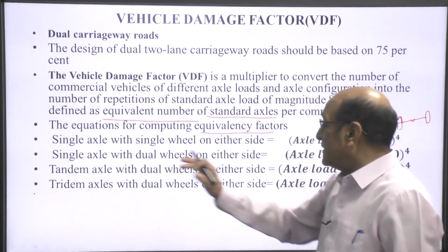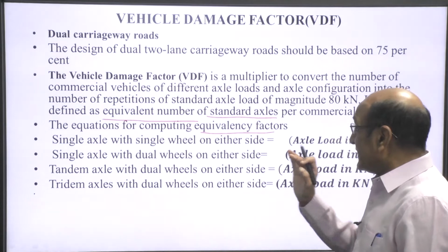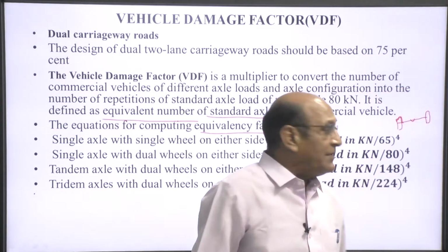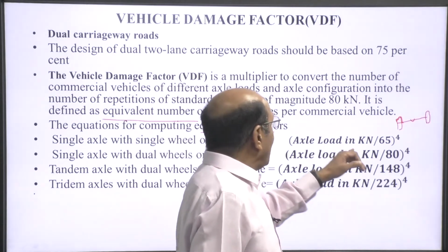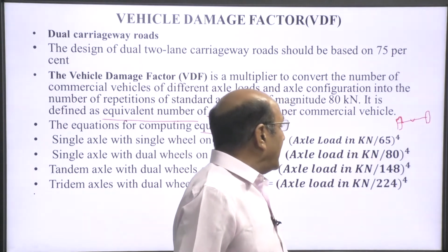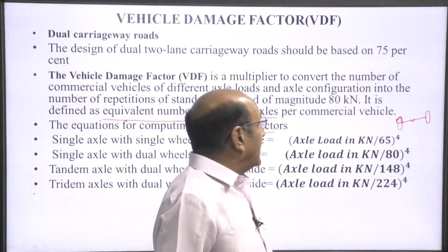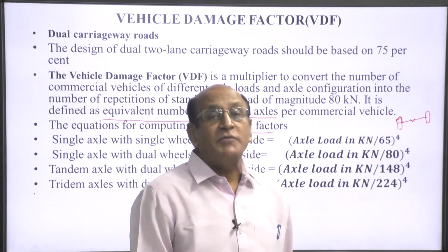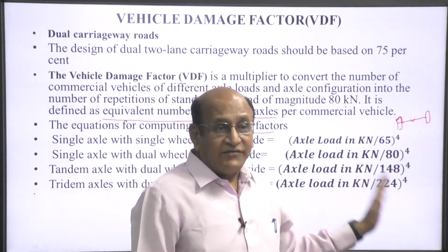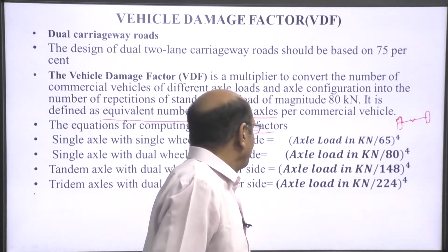For this, the factor will be axle load in kilonewton divided by 65, to the power 4. That will give the equivalency factor.